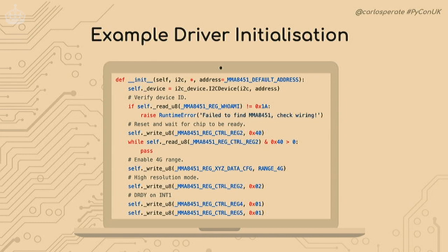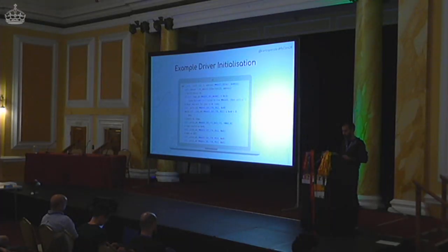And then underneath all of that, we basically have normal write operations. Just like before, they write to specific registers to do some configuration. And we can go back into the datasheet to figure out what's happening. So in the end, MicroPython driver code is not all that different than your average Python code. We just have a slightly different documentation.